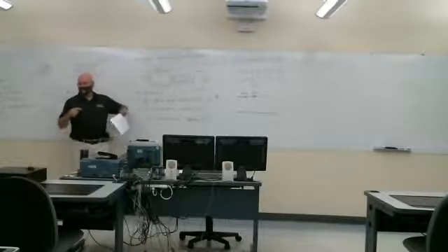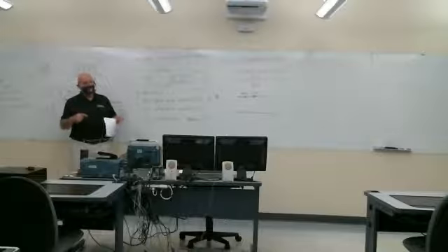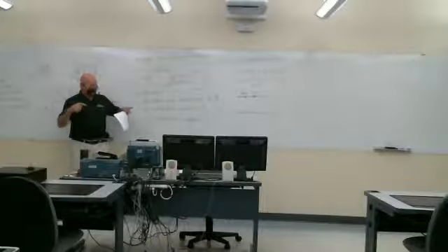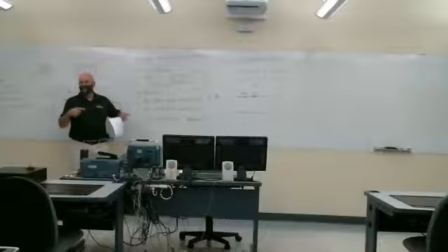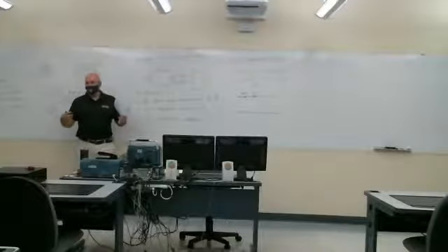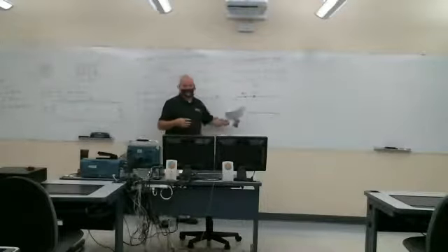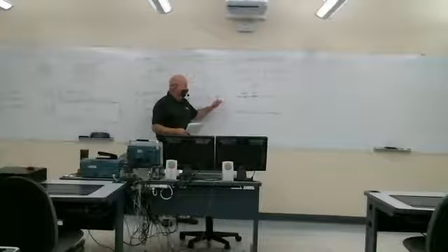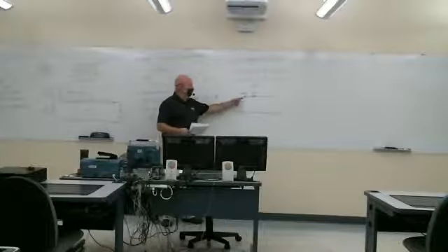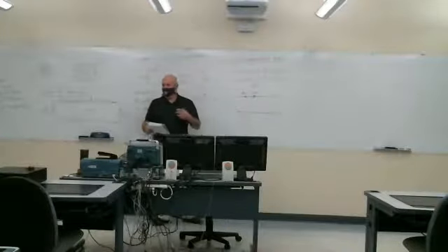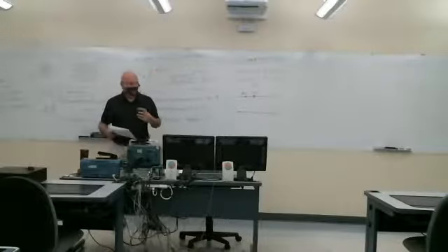And we'll see when we start talking about inductance that just a current flowing through a conductor acts like an inductor. There's a magnetic field set up, there's energy stored in that magnetic field. That is an inductor. So this models that effect. Again, for what we've been using, both of these are short circuits in our traditional model for a wire.